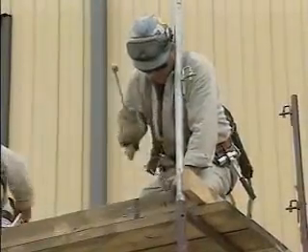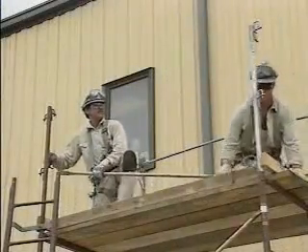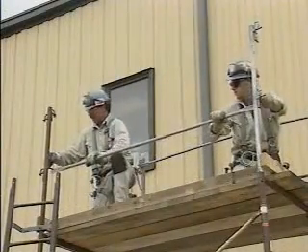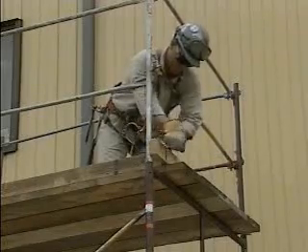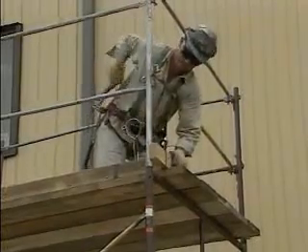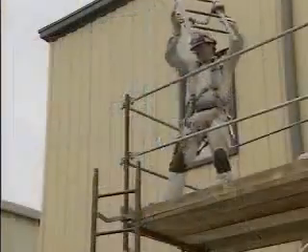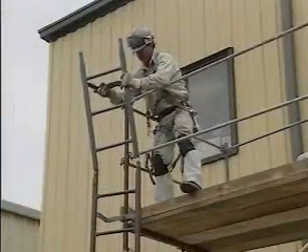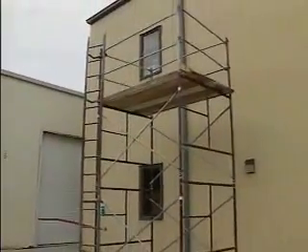Toe boards are then added on all four sides of the scaffold floor, and upper and middle guardrails are connected between the guardrail posts. To complete the scaffold erection, the builders use wire to secure the toe boards and flooring planks to the scaffold framework. Then they attach the final section of ladder to a guardrail post and install a green tag to indicate that the scaffold is safe to use.